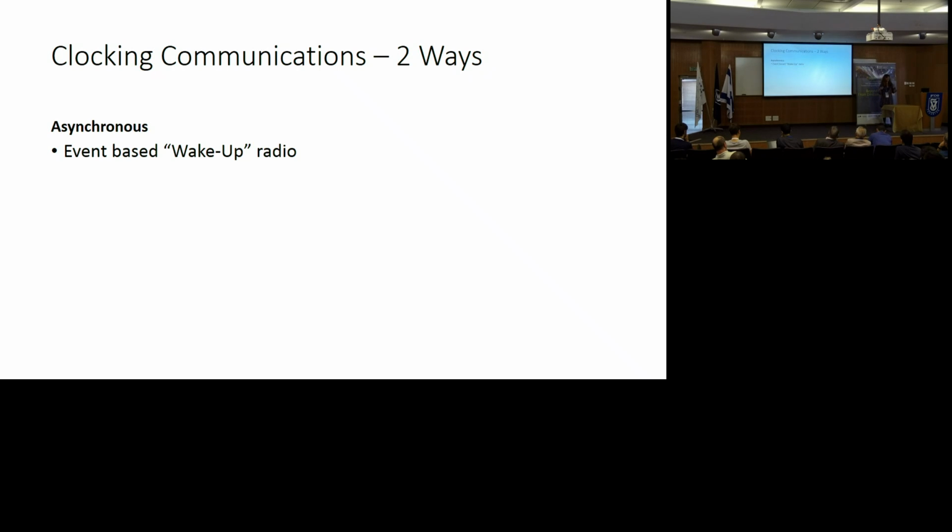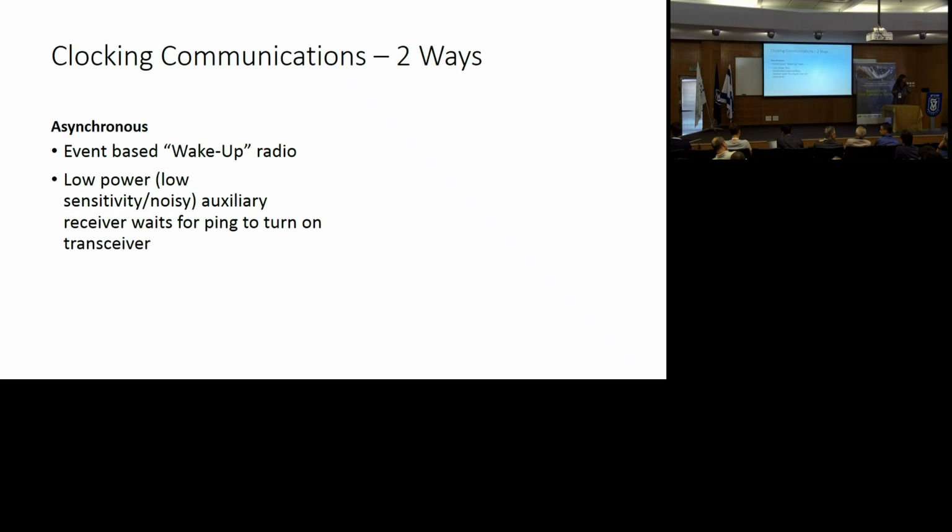And it's actually a horrible radio that consumes very little power and has probably very poor sensitivity. And it sits and it waits for something to bang it, okay? And when that thing bangs it, it wakes up, and then it commences communication, okay? So then it does what you're used to in an asynchronous system, which is some type of handshaking in order to start some kind of communication. So this is one way of doing things, and I'll talk about how new devices can help here.